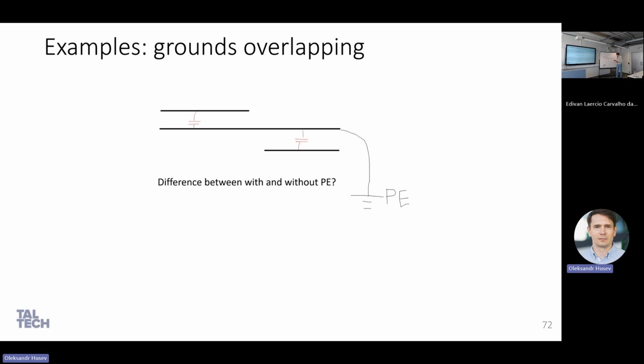And the explanation is the following: if you have a floating metal, and here you have signal plus, here minus, it's like a capacitor, right? But what will happen with this layer? It will have minus and plus, with total charge equal to zero, which means that you have an equivalent circuit like this. And this is a series capacitor between this parasitic capacitor and this parasitic capacitor.